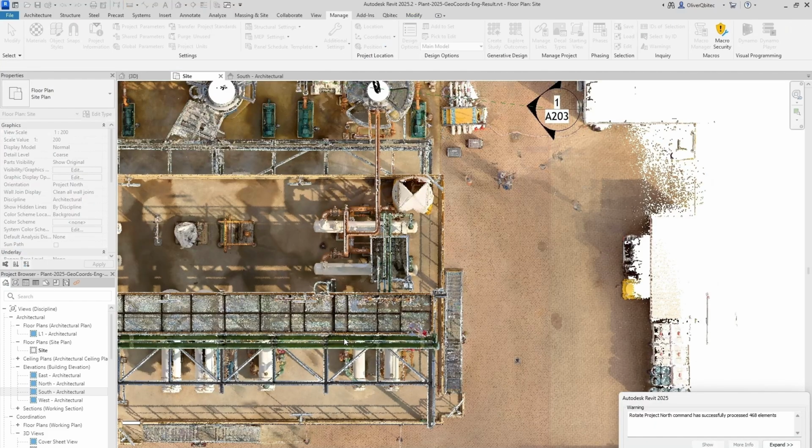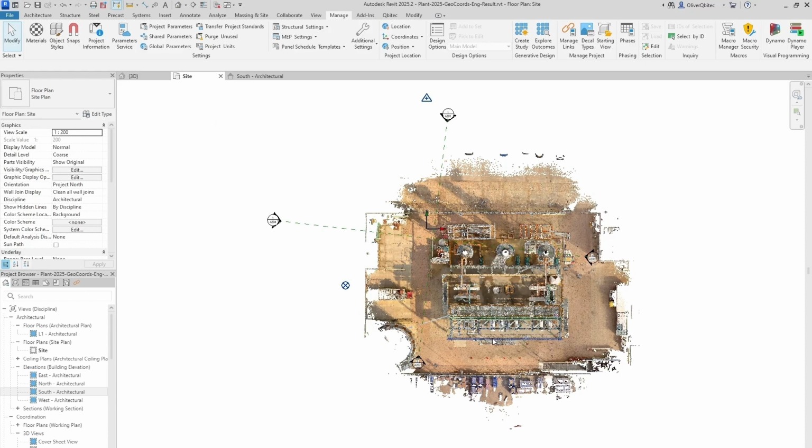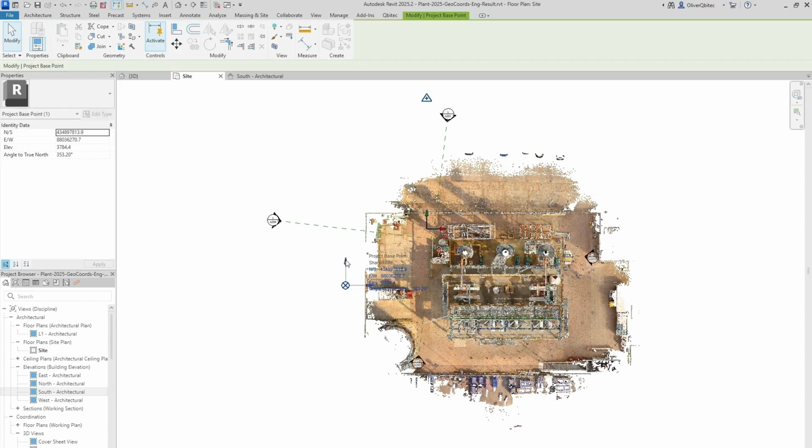Now you have seen that the coordinate system is rotated, not the survey coordinate system, but the project coordinate system. If we look again here, we can now see that the project coordinate system corresponds exactly to the building axis, but the survey coordinate system is still aligned to geographical north. As a rule, I will now move this symbol to a place where I know a georeferenced coordinate, to a boundary stone or something similar. Set the origin of the project coordinate system to a place that describes my project coordinate system well.